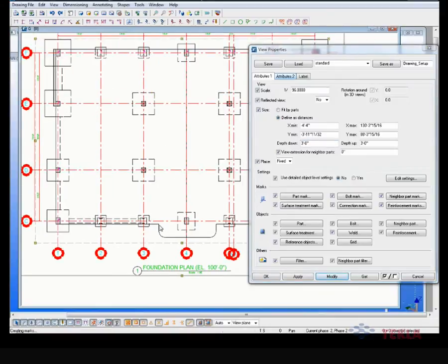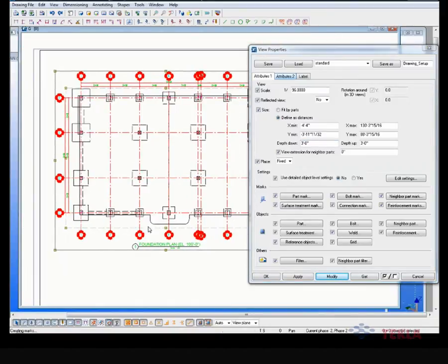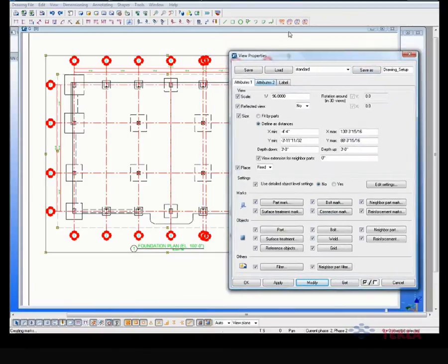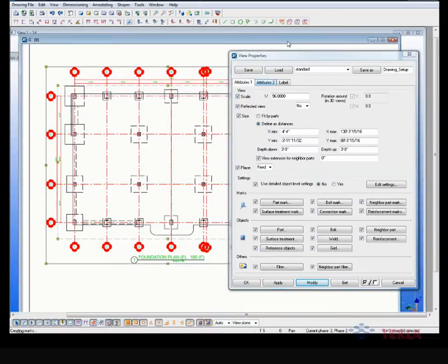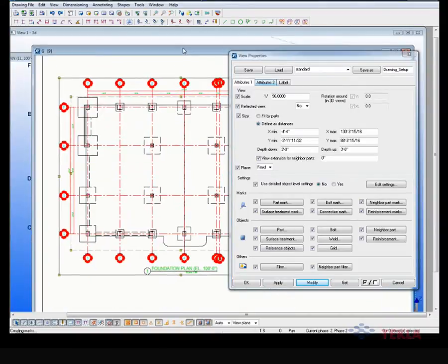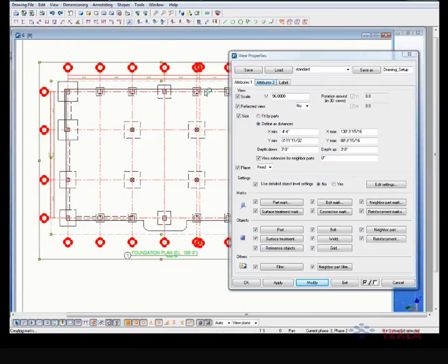So initially you can bring that in from the model and get your drawings created. So I would recommend that before you create your drawing views, like for plans, is to actually make sure and check all your model views to make sure the model Extrema are the way that you would want them to be first. And you can do that by fitting by selected area on each view.